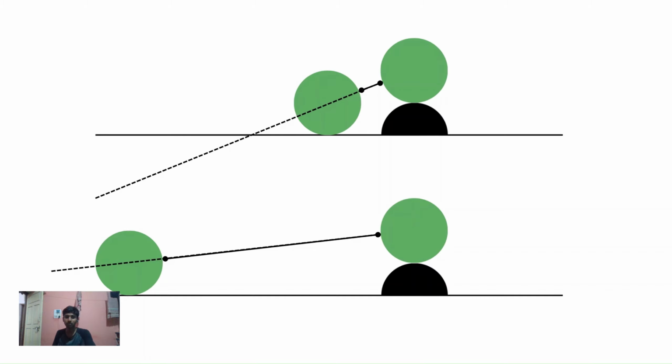Now this is only considering the wheelbase. Imagine when you have a suspension system added in. Of course, the longer wheelbase cars will not feel it at all because the suspension will complement the wheelbase geometry, and the rider inside will never even second guess that an obstruction has been passed over. But in the case of shorter wheelbases, even with the suspension set in, you are more likely to feel the sudden sharp pitches in your motion.